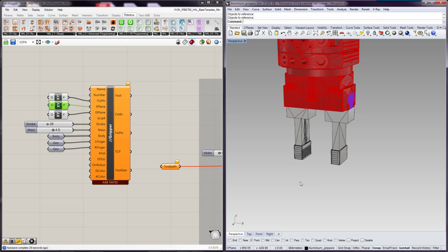Everything that we talk about from here on out will be talked about in planes in terms of pick and stacking. What do they call it? Yeah, pick and placing. It's in terms of the top of the object, so the top plane. We will always be defining planes in the top of the geometry, and it will match plane to plane. So if I have a 50% gripping ratio, which will tell it to match the plane at the center of this to the top of that other plane, that'll dictate how much of the block it actually grabs.